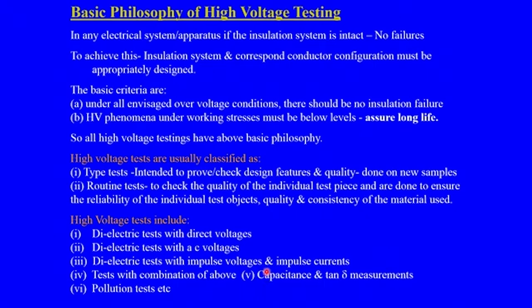Both voltage and lightning currents are normally seen, and the insulator has to withstand both the voltage and the surge currents because of the lightning. So, these have to be tested in the laboratory. Apart from individual tests, combinations of the tests also have to be carried out, and as discussed, the capacitance and tan delta measurements and pollution tests are also essential for better and long life of any insulating equipments.